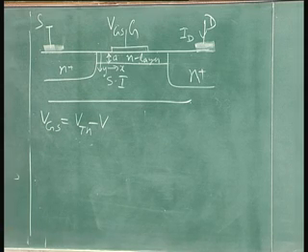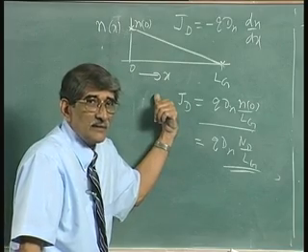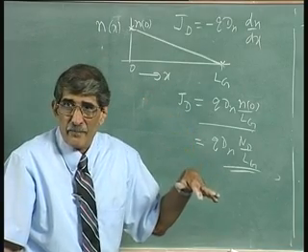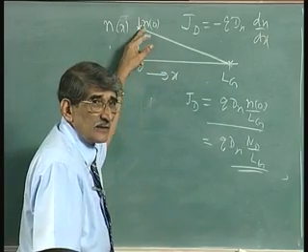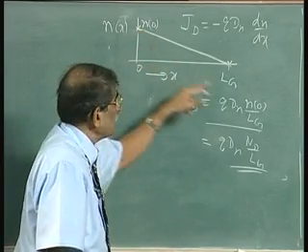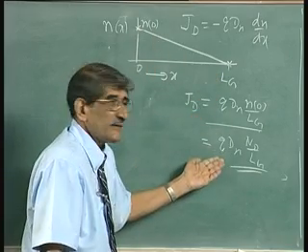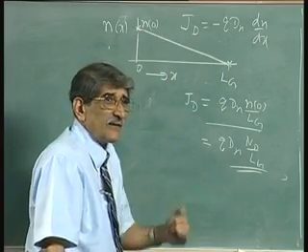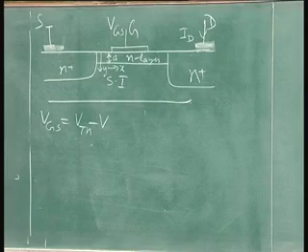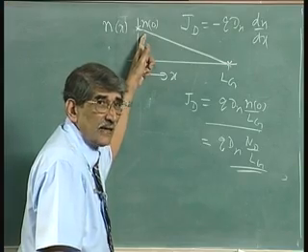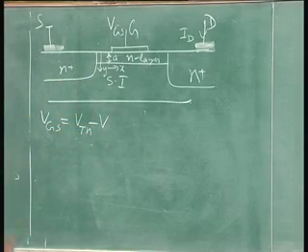You can understand from here that the equation that we have used is similar to the equation of a bipolar transistor. In the base region of the NPN transistor, you have electron concentration raised up, electron concentration 0, and the whole thing is by diffusion. Same thing that we have written here. Now, all that we have to find is, if I reduce the voltage VGS below VTN, what will be this concentration at this edge? That is what we want to see. Let us see what happens.